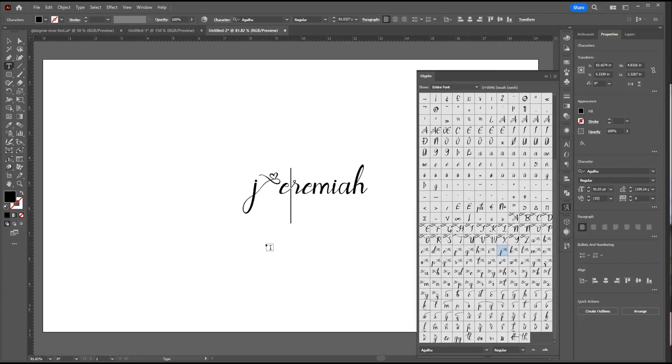I know the mouse is always the first thing you look at, but it gets tedious when you can just use the arrow keys. It's so much easier. So here, I'll show you, if you use Alt and arrow key right, you're saying give me some space between these letters. If you hit Alt and arrow key left, you're saying I want to snug these letters up a lot more than they were. Now you can see both ways. This font already had it pretty nicely done.